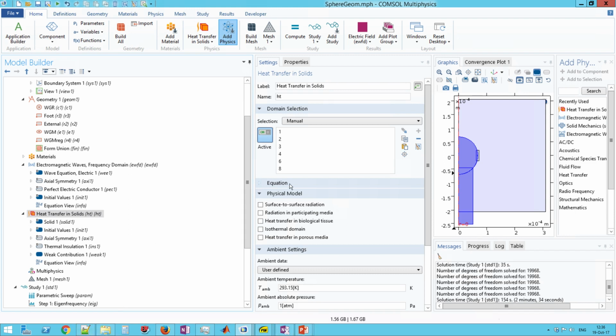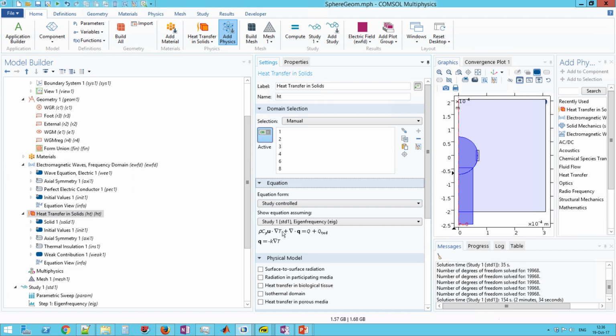So for the heat transfer equation, it is like this. If I go to the cylindrical symmetry, I introduce my temperature in the form of this complex exponent, and after taking this gradient, you will have there i m over r that came from differentiation of your complex exponent over the phi dimension.